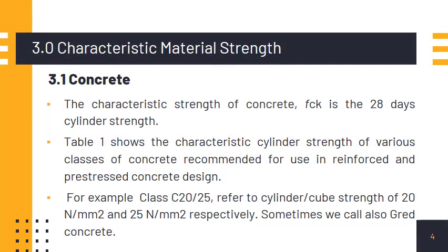Now we look at one by one material in reinforced concrete. First, we have concrete. I'm sure you are familiar with concrete. Concrete mature at 28 days, and normally that time we measure its strength. To measure strength of concrete, we can use cube or cylinder. We have to bear in mind that in design using Eurocode, the strength is measured using cylinder sample. So if we have a cube sample, we can estimate the strength of cylinder. We call characteristic strength of concrete as fck.